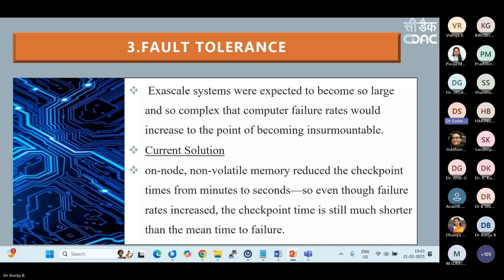For example, sometimes there could be a checkpointing technique. So if there is a crash, I don't start from the beginning, but from maybe just one or two cycles behind. So checkpointing could be one option. Then redundancy: active-active, active-passive, or hot, cold, warm kinds of standby mechanisms with appropriate watchdog timers, so that the baton is passed on to the active or alternate system, and the system does not stop functioning.